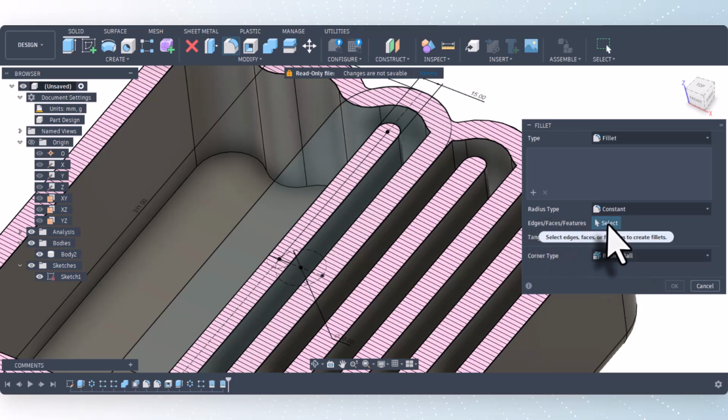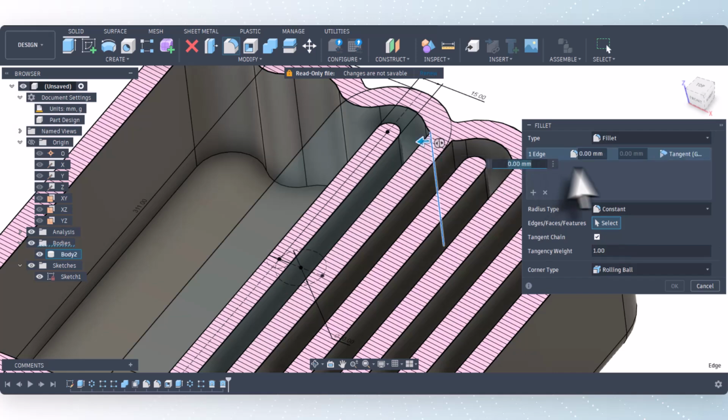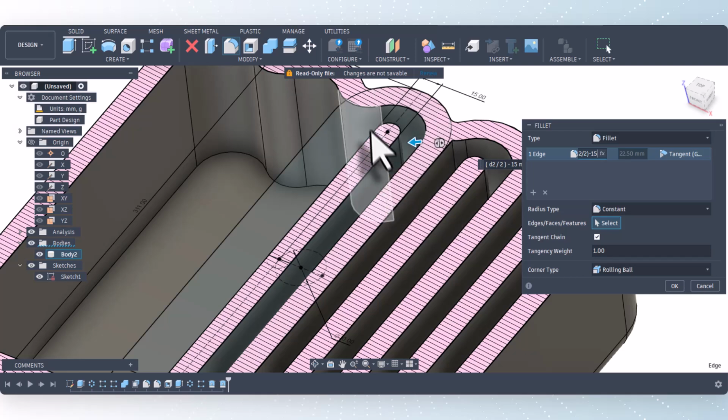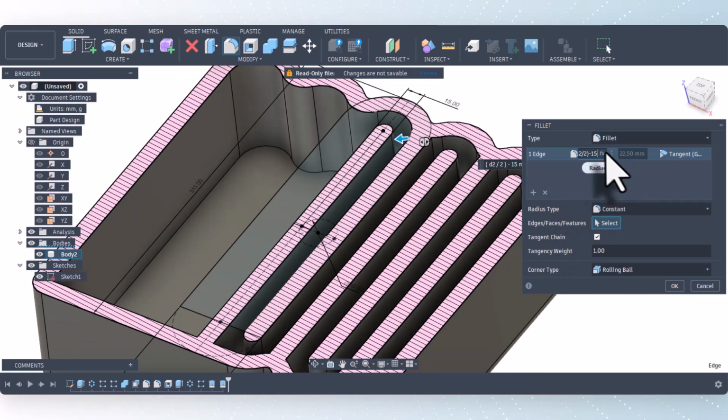Well, I decided to try this again because I did a practice and it worked okay. So I'm going to select this edge, and for the radius, I'm going to do parentheses D2 divided by 2, and then I'll do close parentheses. And so this time it's saying okay. I don't know what I did before. And then I do minus the 15. Okay. And so that time it's doing it. I don't know what I typed in incorrectly before. You got to be careful when you're putting in a formula that you put it in exactly correctly.